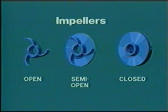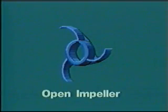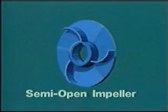There are three types of impellers: open, semi-open, and closed. Open impellers basically are vanes mounted on a shaft with just enough backing or shroud to keep the vanes rigid. Semi-open impellers are completely covered on one side of the vanes. Closed impellers have shrouds covering both sides of the vanes. They also have a central hole or eye on one or both sides. That hole lets fluid enter the impeller.